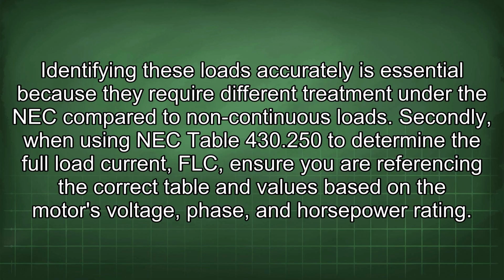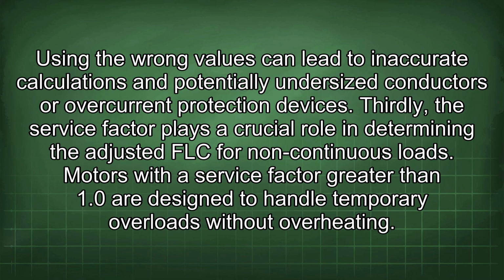Secondly, when using NEC Table 430.250 to determine the full load current, FLC, ensure you are referencing the correct table and values based on the motor's voltage, phase, and horsepower rating. Using the wrong values can lead to inaccurate calculations and potentially undersized conductors or overcurrent protection devices.